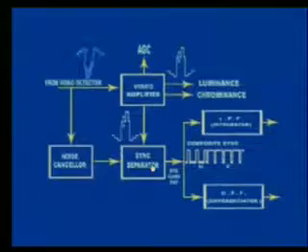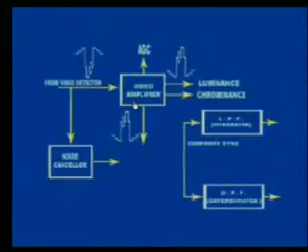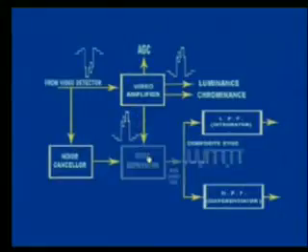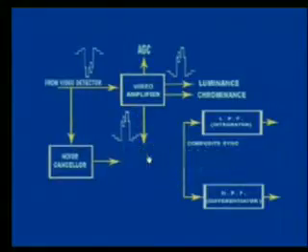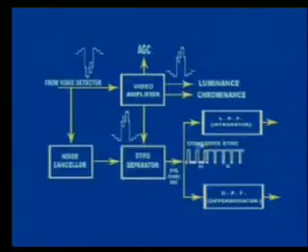The sync separator, which is the topic of discussion, gets the video signal from the video amplifier in the inverted form. And this sync separator separates the combined sync.